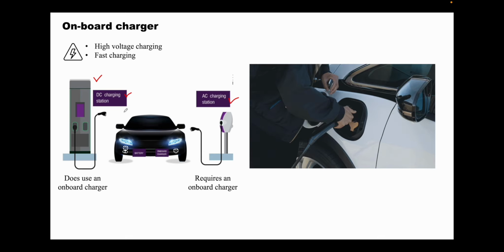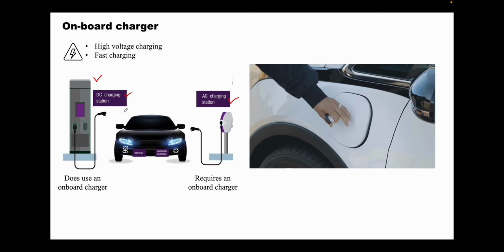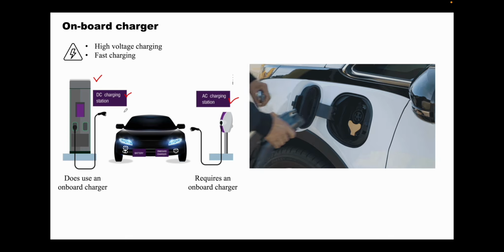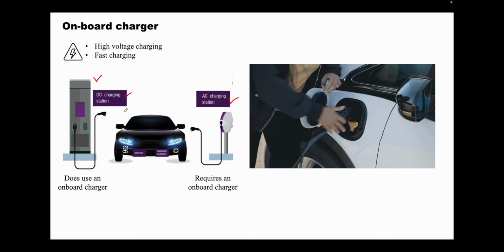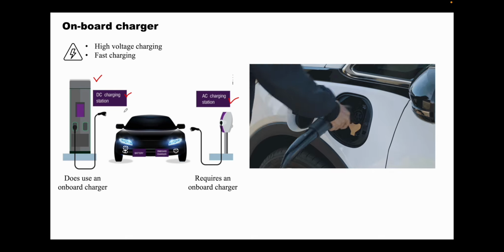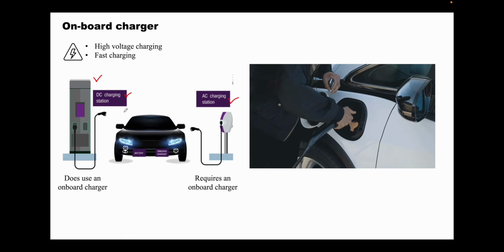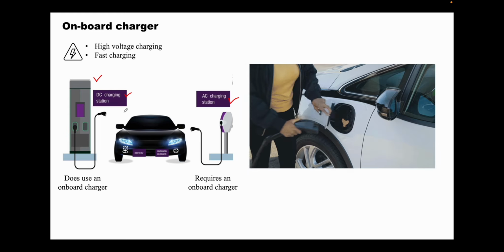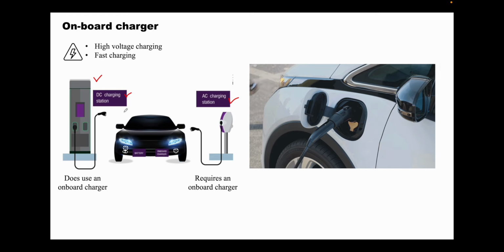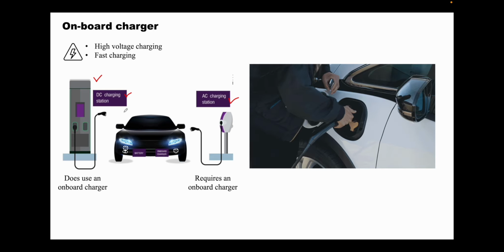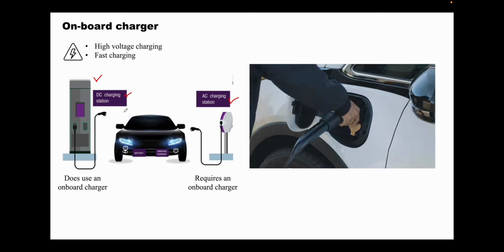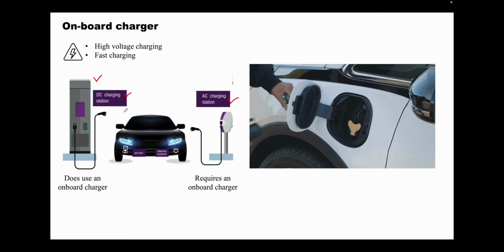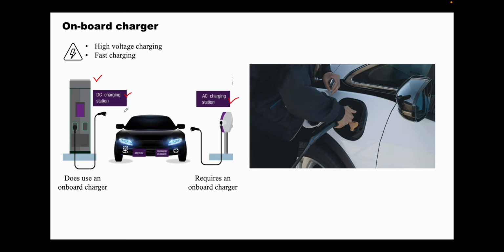So why do we need a rectifier? As we deal with batteries, right, batteries are a DC power source. So whatever the source, either AC or DC, we need a DC power source at the end to charge our battery. While charging the battery, that is called the charging process. In case of DC, you don't need an inverter to do the charging, but as you are using a DC source, you can directly charge your battery, but with a controlled current.